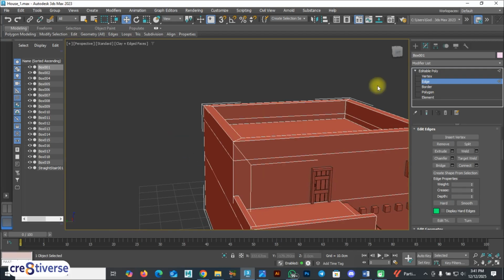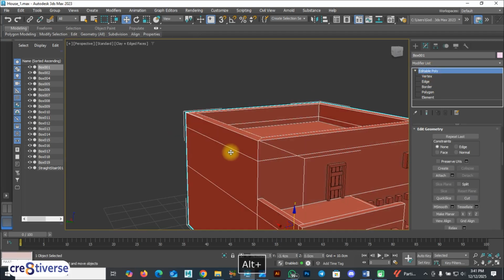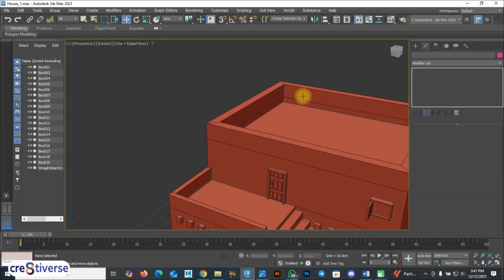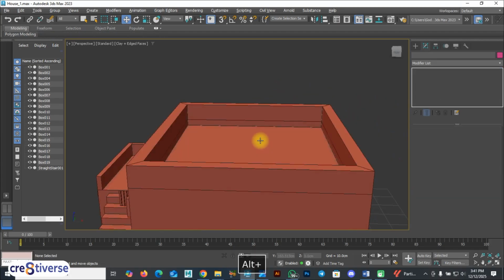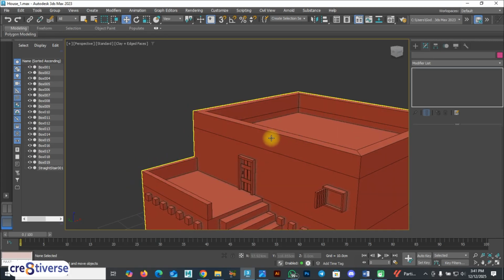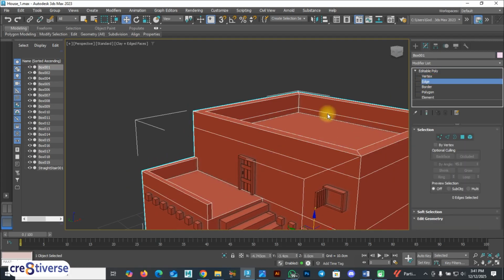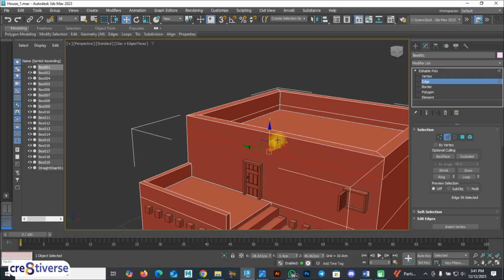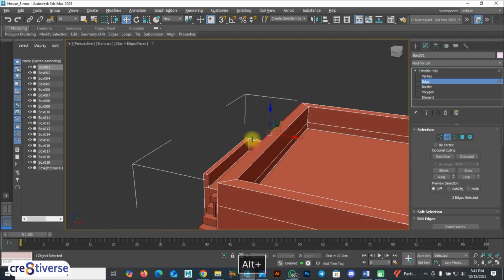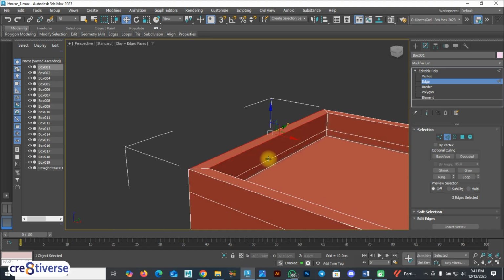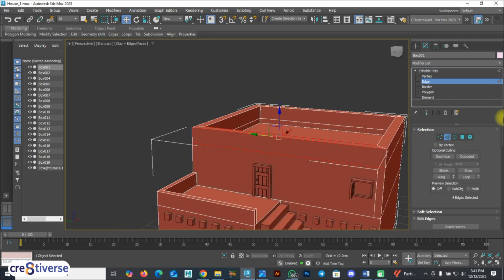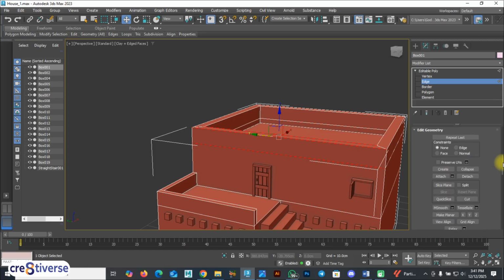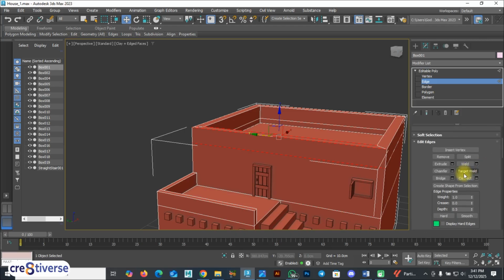now, this line inside and the one outside are on the same spot, or point rather. So go to my edges, click this, hold down Control, click this, and click this, and go to connect. Okay, go to connect. So I'm going to connect this. Okay, so we're having this now.